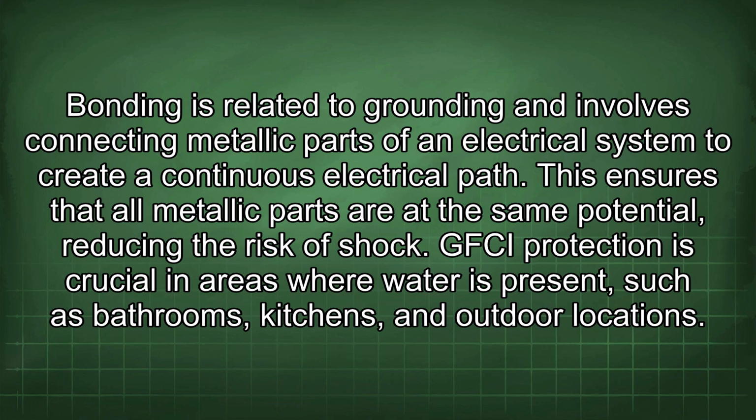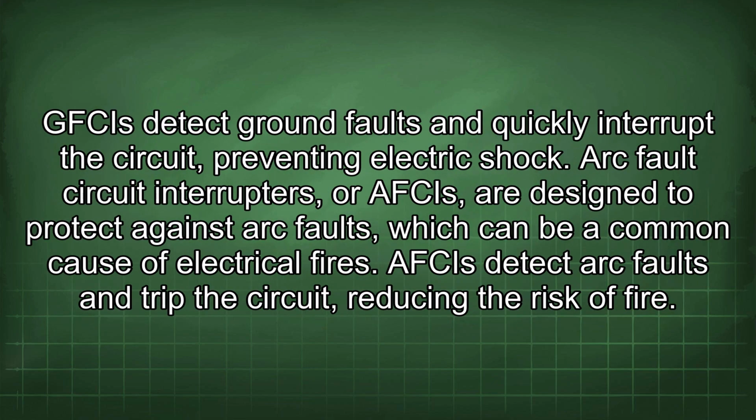GFCI protection is crucial in areas where water is present, such as bathrooms, kitchens, and outdoor locations. GFCIs detect ground faults and quickly interrupt the circuit, preventing electric shock. Arc fault circuit interrupters, or AFCIs, are designed to protect against arc faults, which can be a common cause of electrical fires. AFCIs detect arc faults and trip the circuit, reducing the risk of fire.